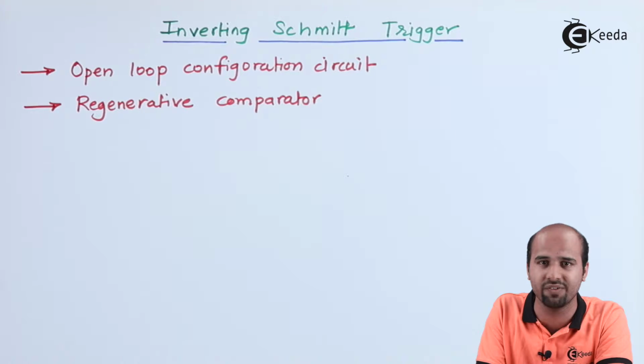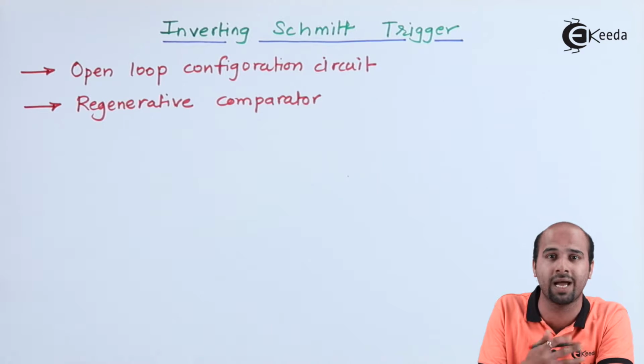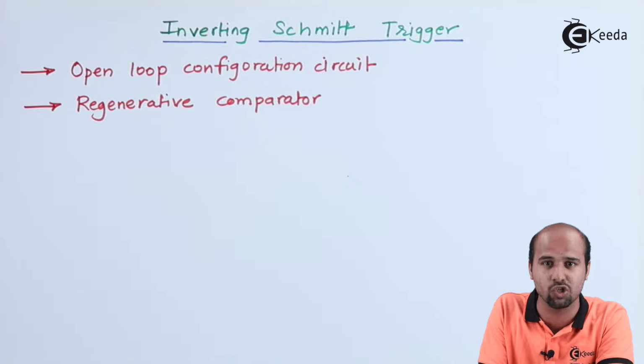Many a times in Viva session, people ask that whether the Schmitt trigger is an oscillator. The answer is no. This is because we are applying the input. But as far as oscillator concept is concerned, we are not applying any kind of input AC signal, but still we are getting the output signal, that too in sinusoidal in nature or faithful in nature.